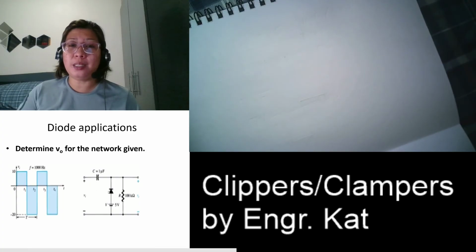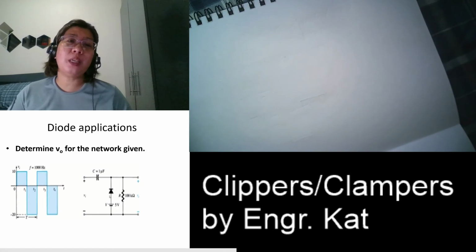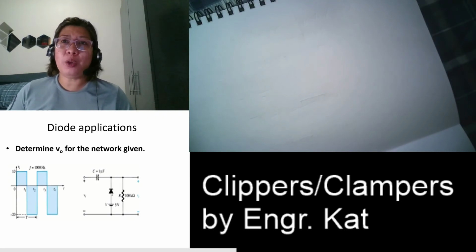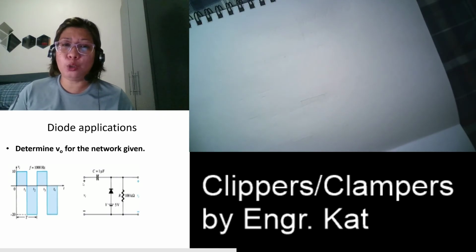So in this case, this is reverse biased. So that is the time when we skip the positive half because we always have to start during the time that your diode is in the forward bias mode. And when will that happen? That will happen if this is minus and this is plus, and that is during the negative half cycle.